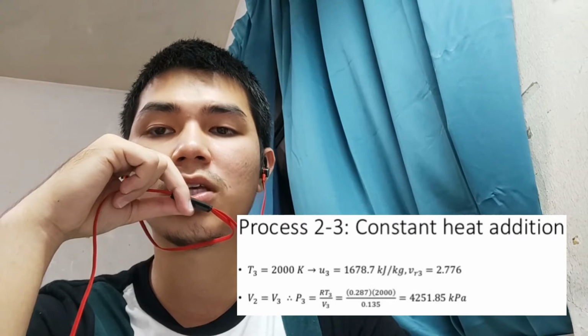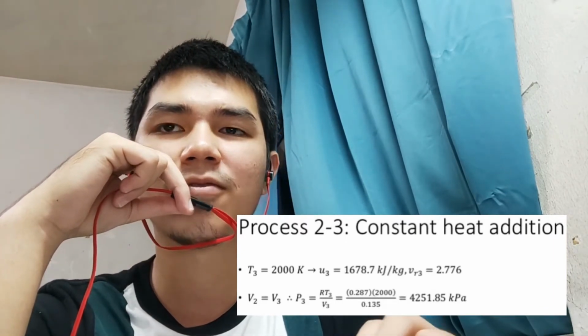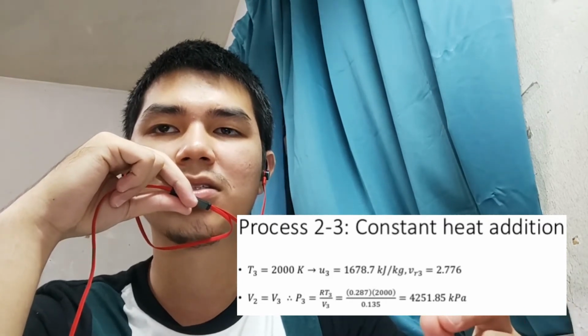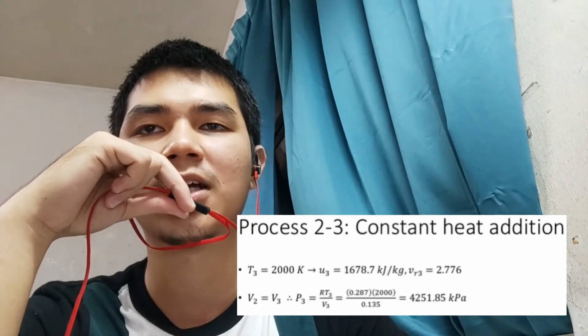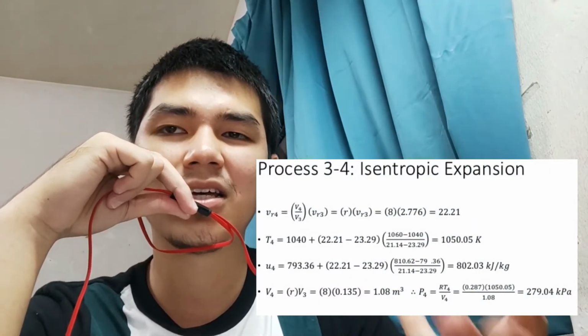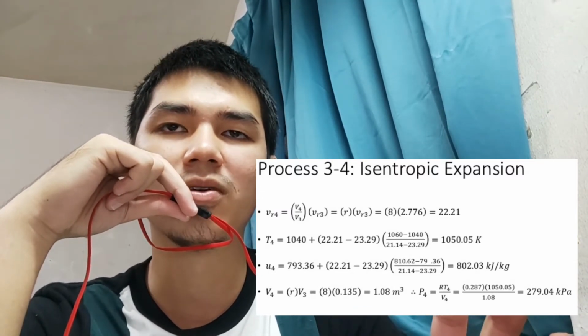Process 2 to 3 is a constant heat addition, so it is quite easier for us, where we get the values from the steam table only for the third temperature, which is 2000 Kelvin. So the pressure we got is 4251.85 kilopascal. For process 3 to 4, the isentropic expansion, we need to use a similar calculation to process 1 to 2.